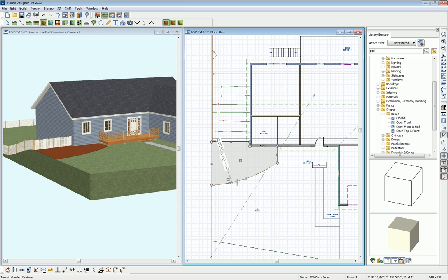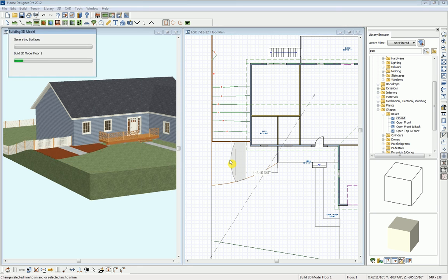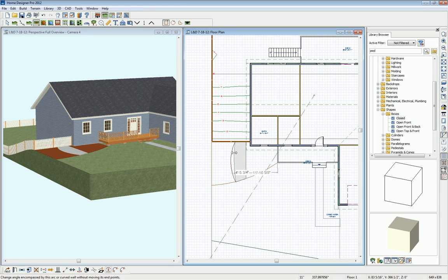I'd like to have a little walkway. So instead of using our garden bed tool again, I'll use our terrain features. With the terrain features, I'm going to select this rectangle and then just do a little rectangle here and alter this a bit. So we'll drag that out. And I really like this arc tool. Really easy just to curve things out. So I'm going to do that same curve on the other side. I'm going to do the arc tool and then just single click on this triangle and drag it over.